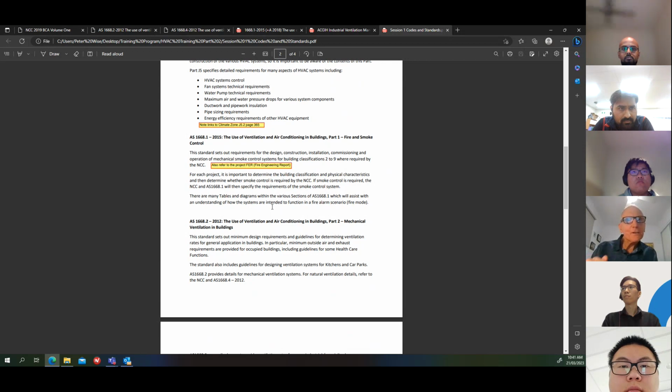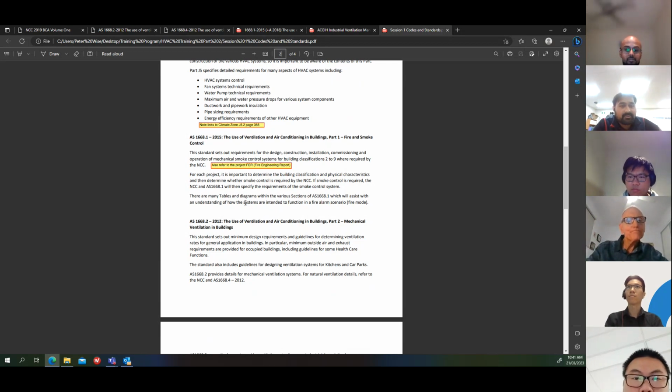If the FER doesn't say anything, it doesn't mean you don't have to do anything. Okay, that makes sense now. So both need to be referred. As a DNC contractor, we need to make sure we comply with 1668.1 and 2. So we can't fully rely on the fire engineering report. No, that's right. If it changes something, you can do what they've asked. But they also might ask for something that's not in the NCC or AS 1668, and then you'll have to do it. So each job's different and needs to be treated on its merits.